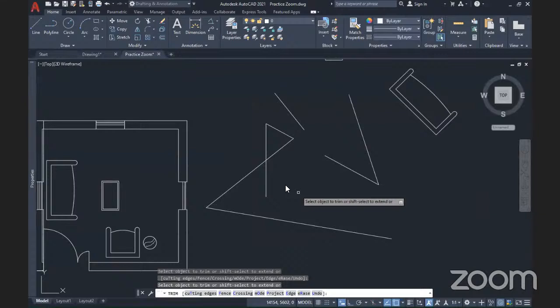If you understand this, please say yes. Okay, John Paul does. Now that is it for the trim. You need to have a boundary for you to trim something, and you need to have the line you want to trim extended across the boundary for you to trim. I believe that is clear enough.